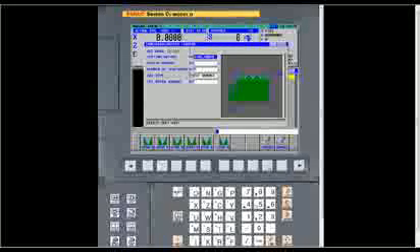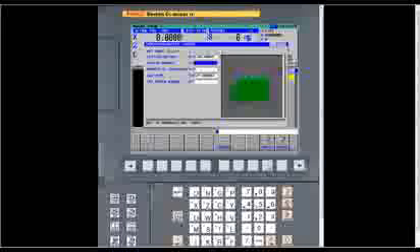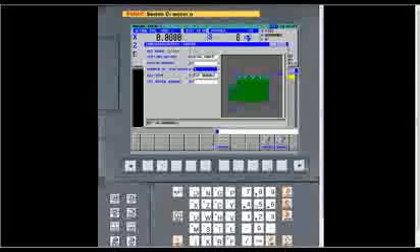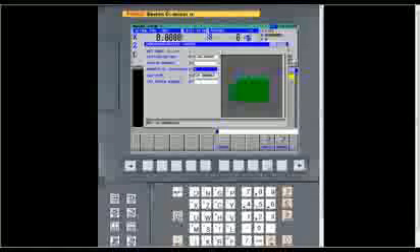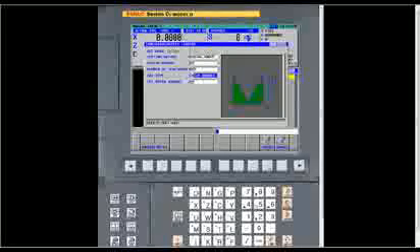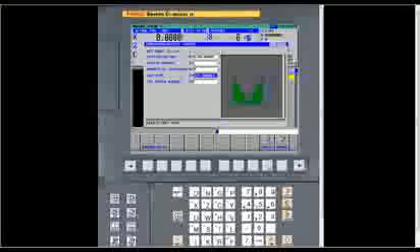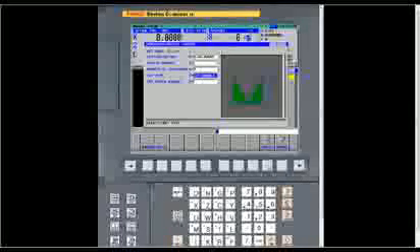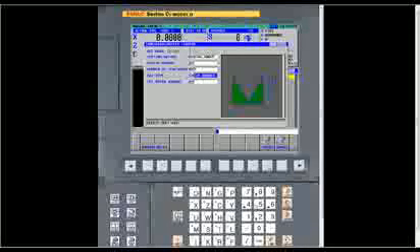But you've got six different ways of feeding into it. The finish amount, you could leave a particular amount of finish stock or a particular number of finishing passes. And then also you can have cut type. You can have number of passes or depth of cut. Those are your 2 choices. I'm an old engine lathe guy, so I'm used to cut number. I've got in my head how many passes I want to take, so I always use that. But some people always think in depth of cut. That's all right, too. It'll work both ways.